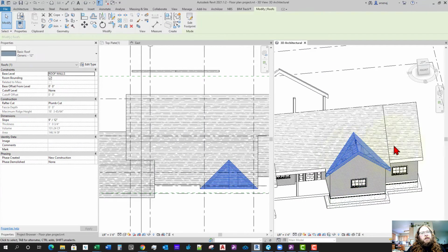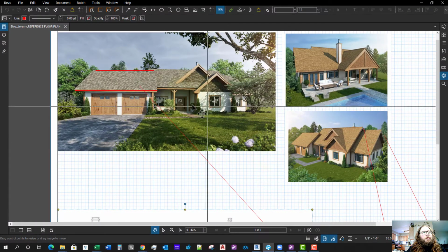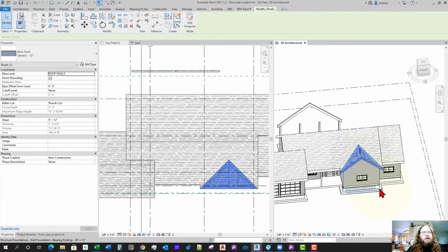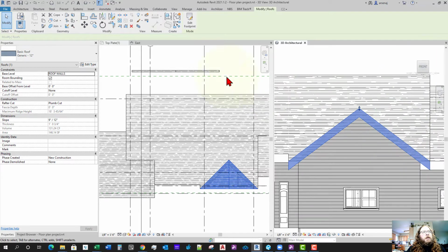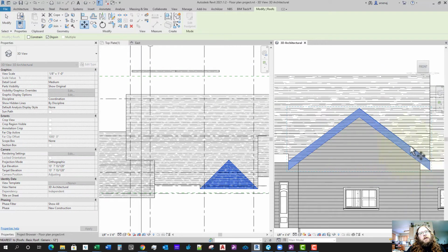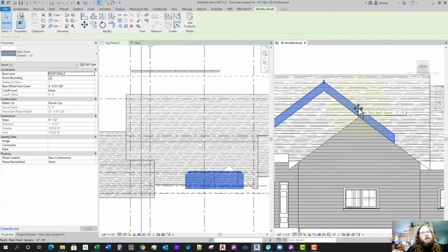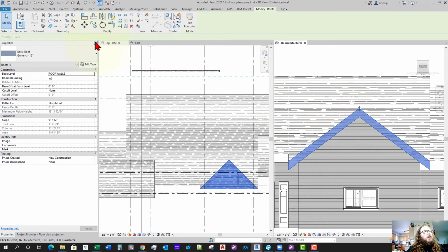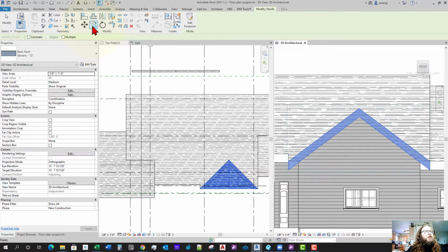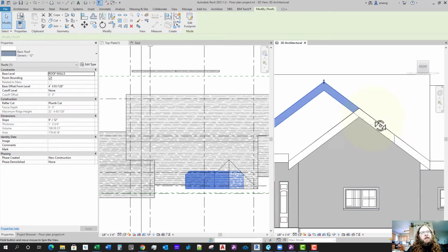While we're here, let's create that double featured roof here. So what we'll do is I'm going to take this gabled in. I'm going to go to the front view of my 3D view. I'm going to hit move. And I'm just going to pick the midpoint and move it up to the peak. Oops, I'm not going to hit move because I want to hit copy. So I'll go over here to Modified tab, pick that midpoint, come up here to the peak, and then pick again, and then we'll pan out.